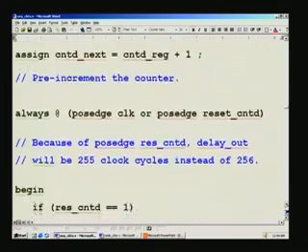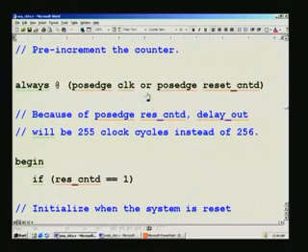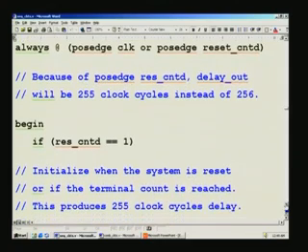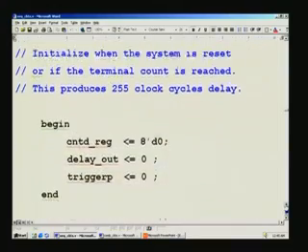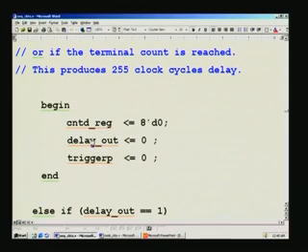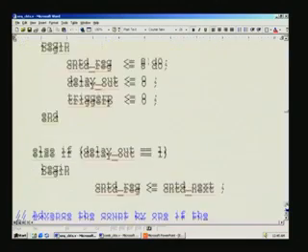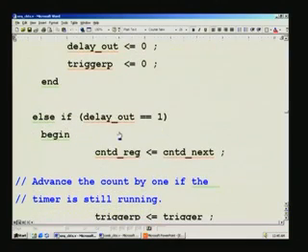And we have an assignment of always block which does the actual sequential work. So that's namely the counting, and that's what is here, and with reset condition being satisfied, you reset the system. All these different counters, delay, output, and there is internal storage for trigger condition to store the previous status as such. That's what is here. And if delay timer is already running, it would have been forced to 1. So long as it is running, then only you do the incrementing. That's why this increment is here, right.